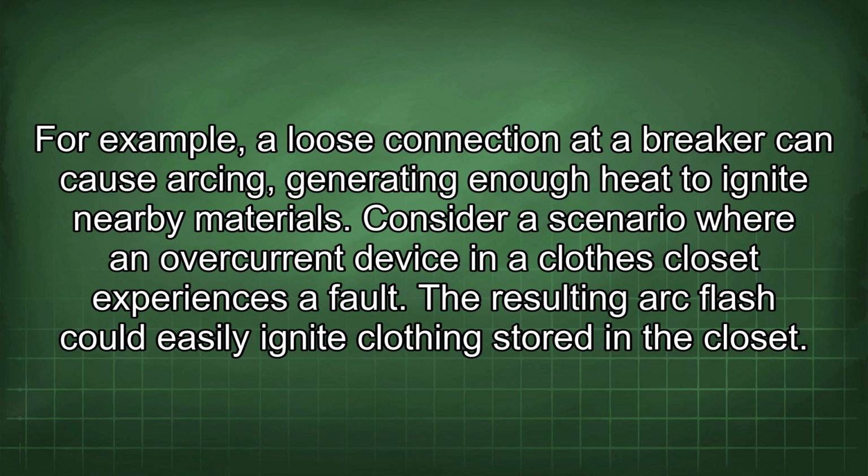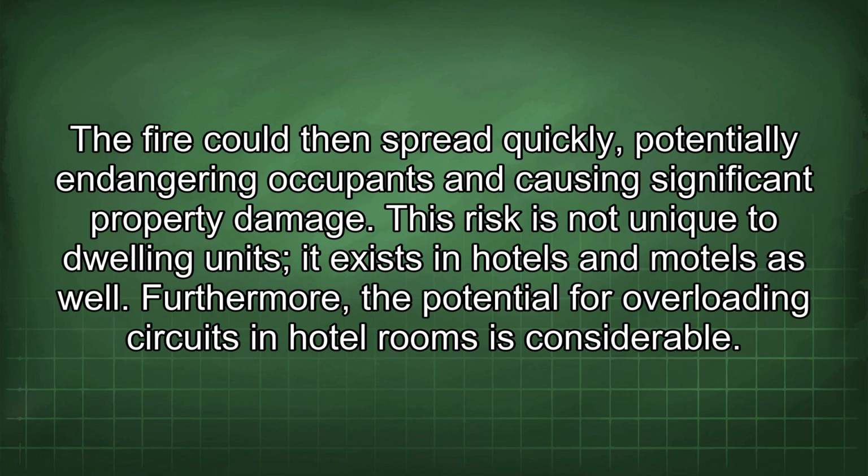Consider a scenario where an overcurrent device in a closed closet experiences a fault. The resulting arc flash could easily ignite clothing stored in the closet. The fire could then spread quickly, potentially endangering occupants and causing significant property damage. This risk is not unique to dwelling units; it exists in hotels and motels as well.